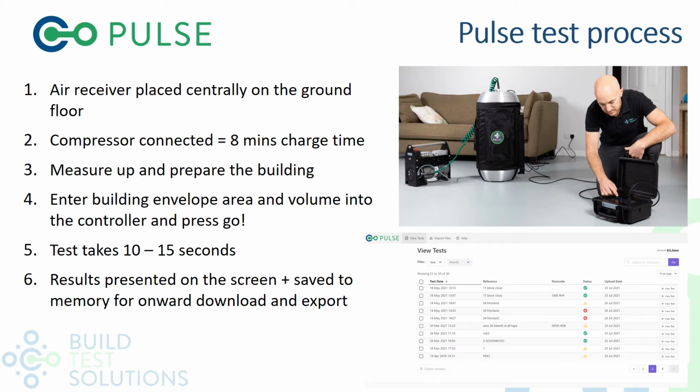And the actual measurement is taken at what's referred to as the quasi-steady point. That is to say, when the airflow out through the air receiver is equal to the airflow out through the gaps and cracks in the building. So there's this momentary phase within the burst of air sequence that the measurement is actually carried out. The results are then presented immediately on the screen, can be saved and exported on a USB stick, and then we provide an online dashboard for analysing and generating reports from results.